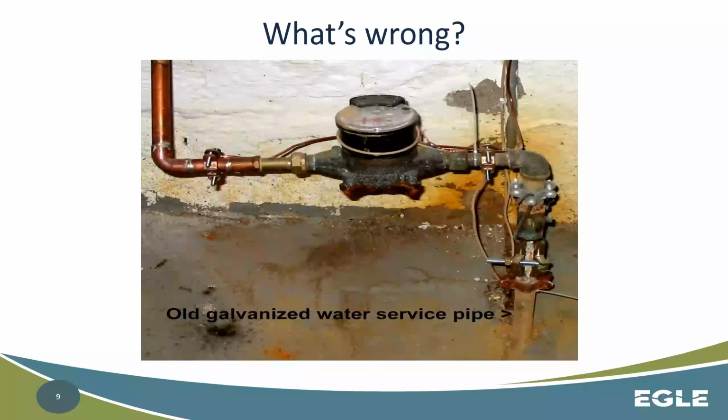And then we have installations like this. So the first issue that I see here is that there's no isolation valves around this meter.